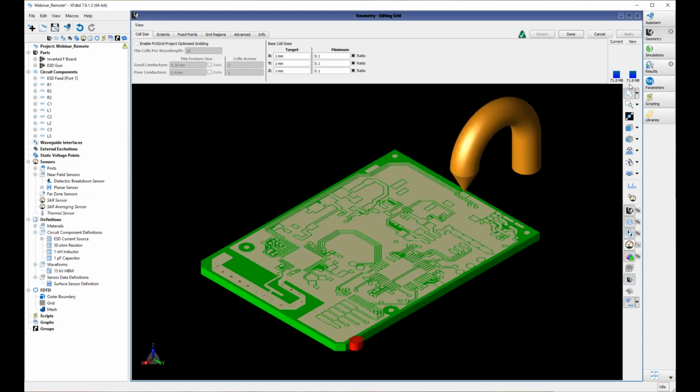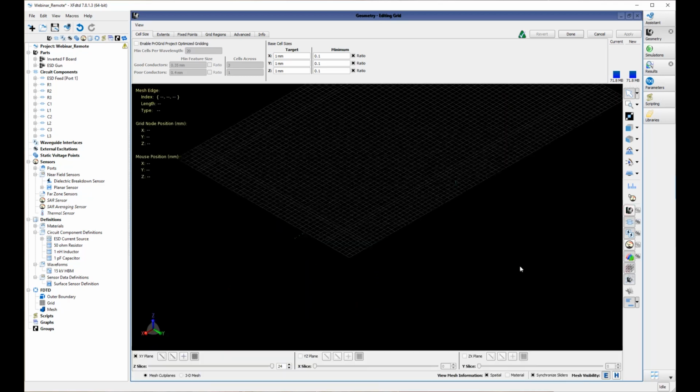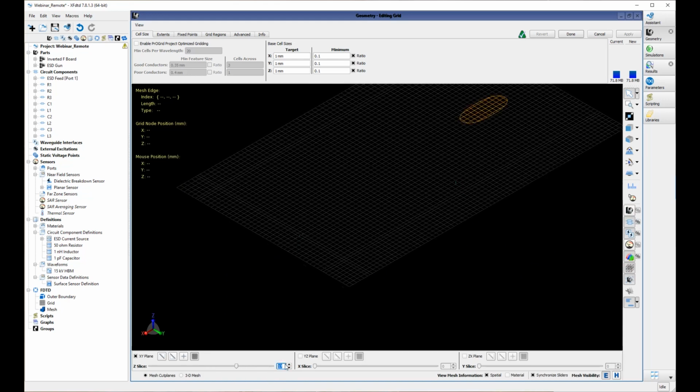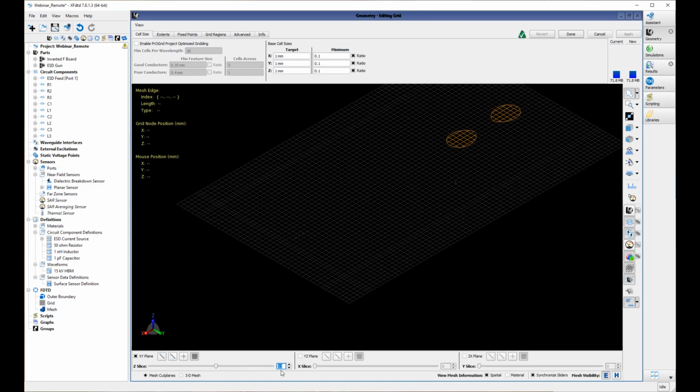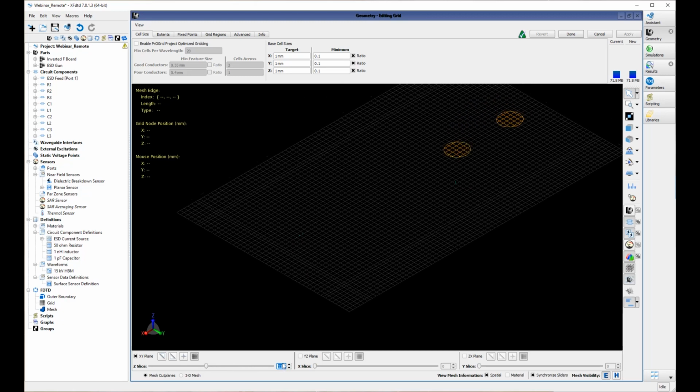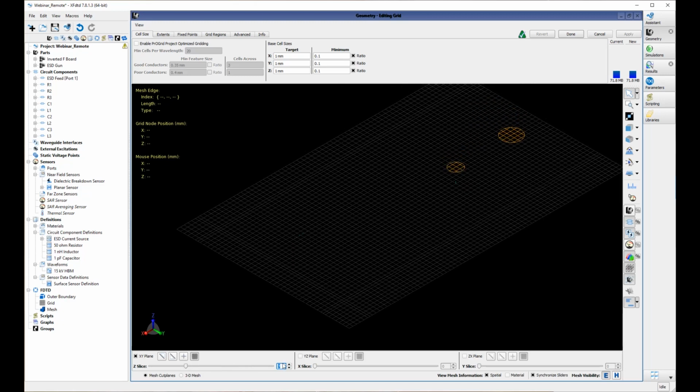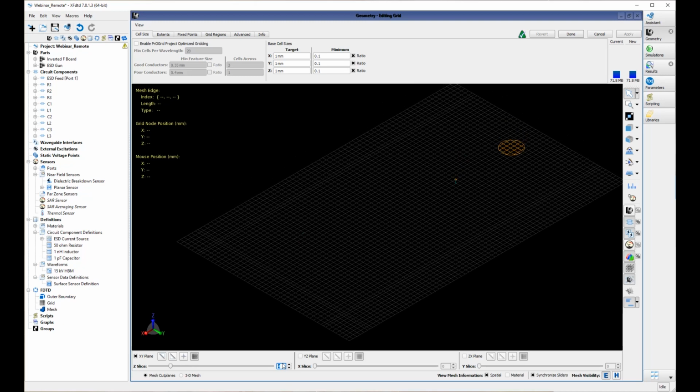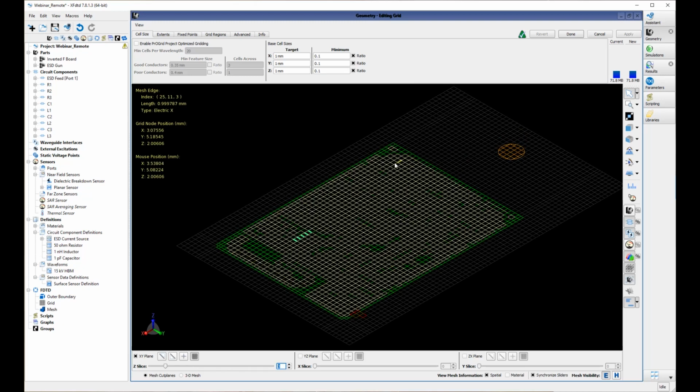At that point, we can go ahead and apply this, and you can see it's only using 71 megabytes of memory. So that's a really coarse mesh. If we pop over to the mesh view, I think what we're going to see is that just with the 1 millimeter default cells, we're not going to be accurately representing the PCB, by a long shot.